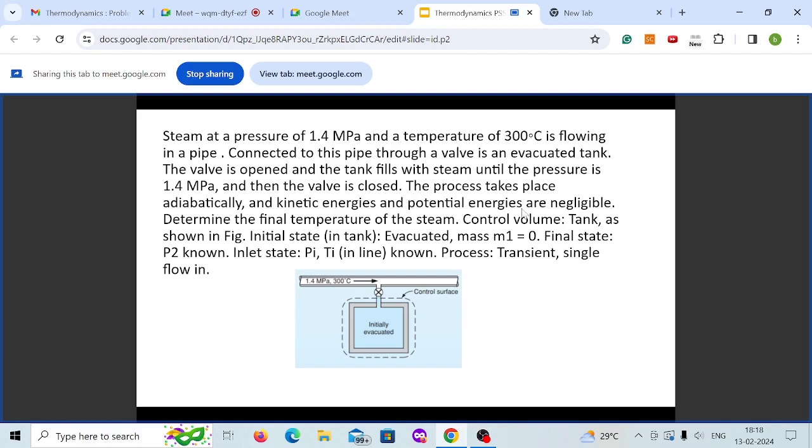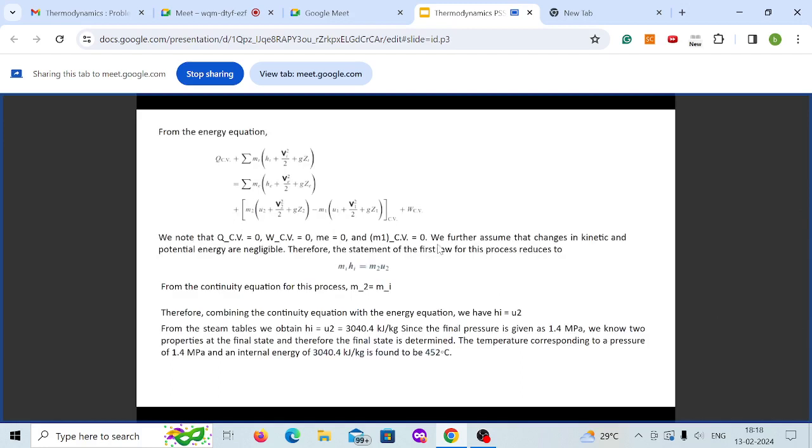So what we'll write is a steady flow energy equation. We'll write a generalized steady flow energy equation. The steady flow energy equation is nothing but an energy balance for the control volume system. Previously we saw the control mass system in the previous week. So here we will see the control volume system. Again, the steady flow energy equation is an energy balance. You see what all energy is coming in, what all is going out, and you balance it out.